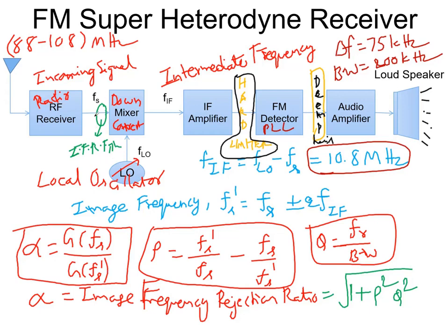But the advantage here is that your detector is always working on an intermediate frequency signal. That's why you are able to stabilize your Q. Whenever your Q is stabilized, your circuit will function better over a long range of frequencies. That's how you can improve some of the parameters of the receiver. Fidelity you can improve, and sensitivity and selectivity also can be improved.